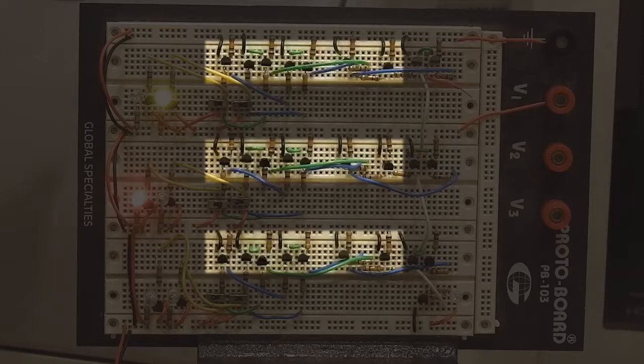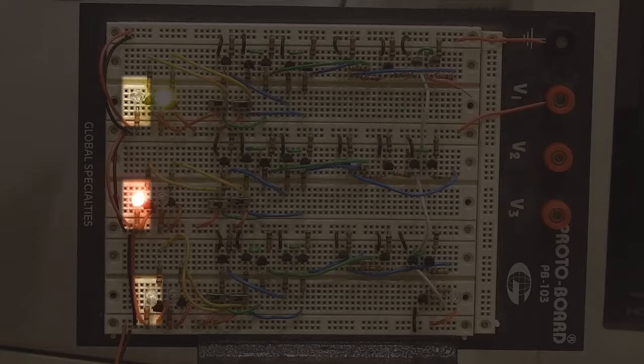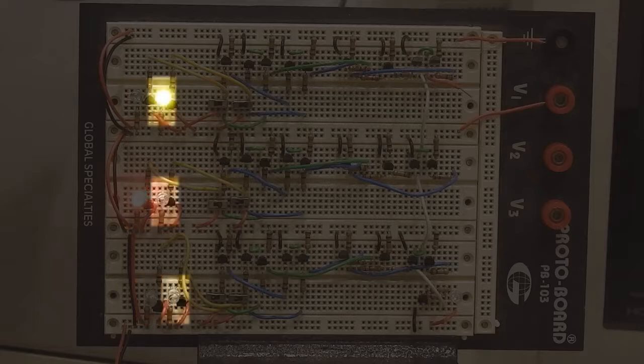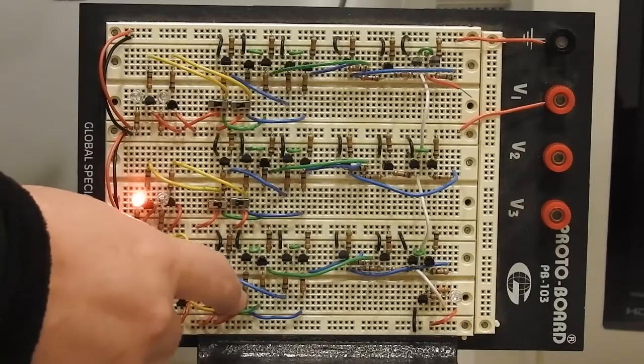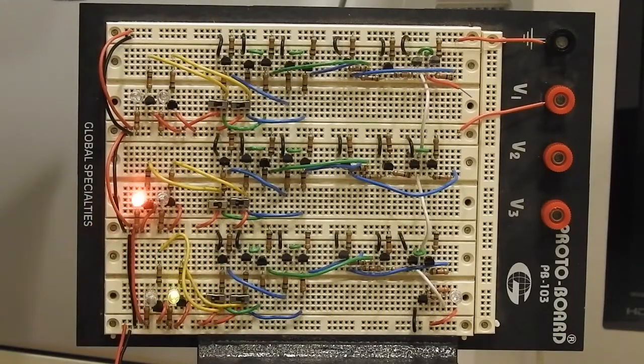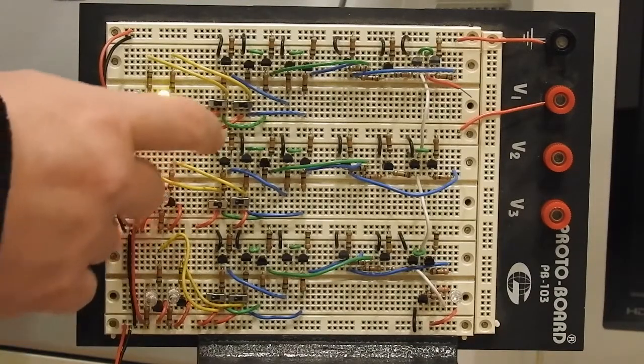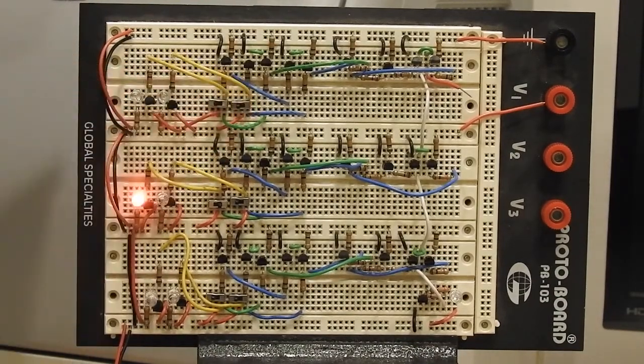And these transistors represent the rest of the logic in our logic gates, the two ANDs and NOT circuits of our previous diagram. These LEDs show the input data line states, and these LEDs show which circuit is enabled. This LED in the bottom right shows the state of our bus. As we enable each gate in order, notice the LED at the bottom right changes state to match the input data line. But what happens if all of the gates are turned off?